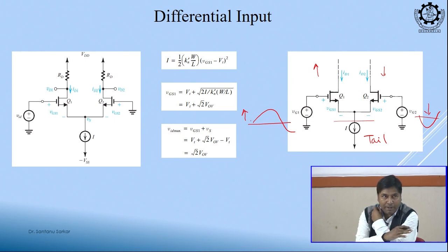Now, on top of the previous DC voltage VCM, I am having a VCM here, but for the AC analysis what we do is consider all the DC sources grounded. So we consider that VCM is not there, but actually it is there. I am doing only the AC analysis.